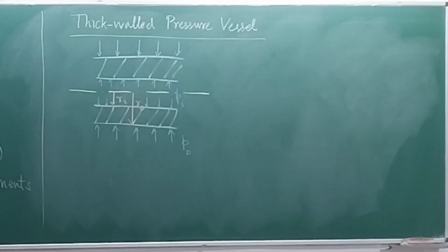There have to be extra conditions, of course, but what I'm trying to say here is that if you have a thin plate, it is not going to be plane strain. If you have a thin plate, if any plane thing is going to happen, it is going to be plane stress. And if you have a long member, if any plane thing is going to happen, it is going to be plane strain.